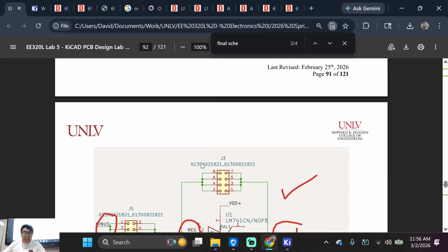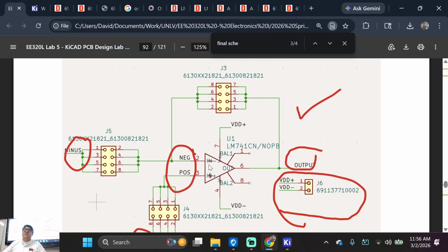We're doing a feedback path. Do you see this minus terminal? That's why they failed the lab, because they put the plus to the output. They did positive feedback. Failed the PCB lab, failed the verification lab. They're like, whoops, my thing's saturated. Verify your things. Luckily for you guys, I'm not making you do a simulation for this lab. I did it for last year's lab, but this one, don't worry.